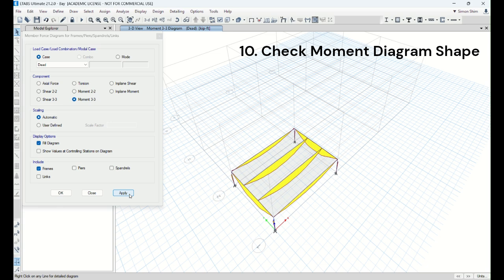So this is the model I show you due to the self-weight of slab and steel, right? Pushing load along the beams generates a positive moment, right? WL square over 8. You remember that? Yeah. That's it. Because this is momentless, 0 moment, 0 moment, right?